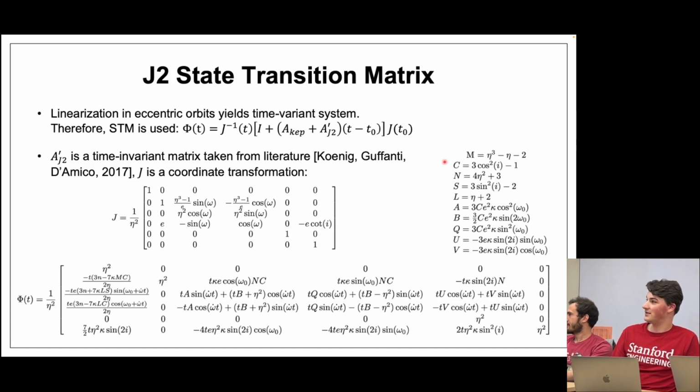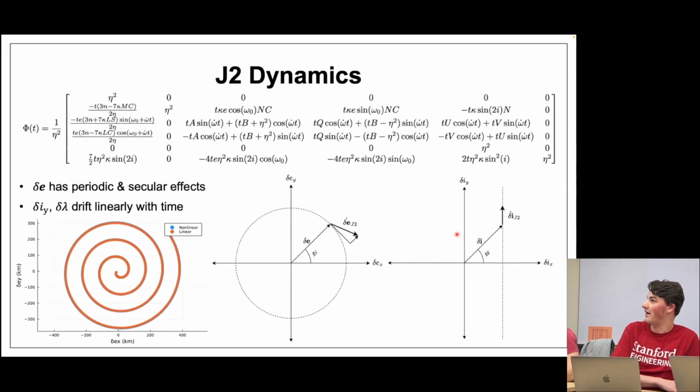And so I took this straight from literature, and then I found the rotation, the coordinate transformation to go in between sets of ROEs, and ultimately arrived at a state transition matrix for my two ROE sets. And this is valid for both because they share a first order equivalence. So there's a bunch of substitutions here, and we're now going to talk about what this state transition matrix does. This is the point of the fifth slide.